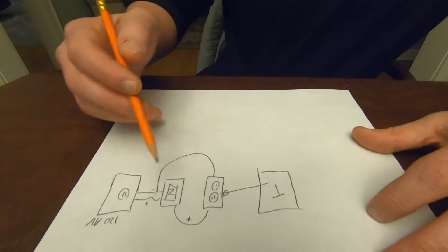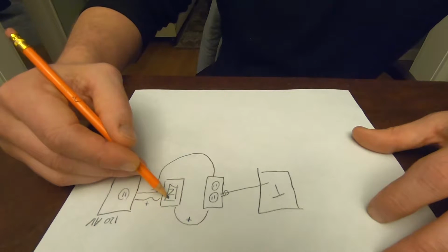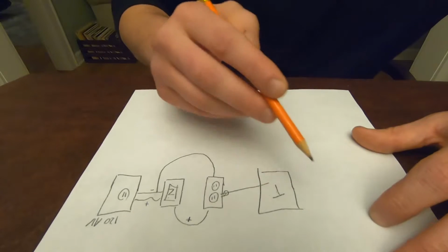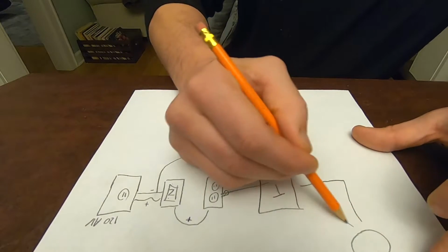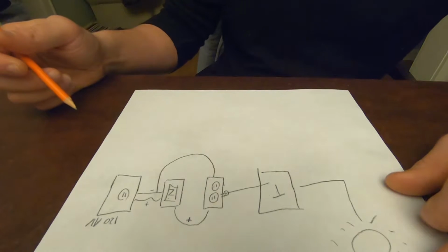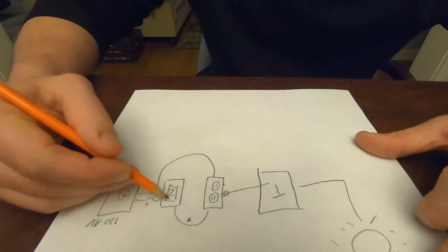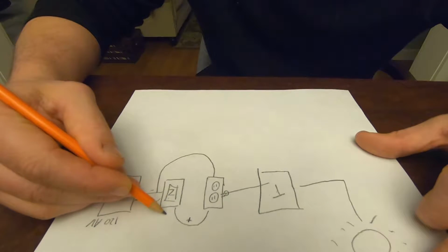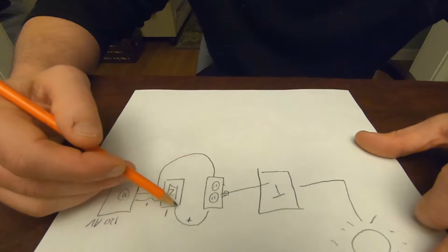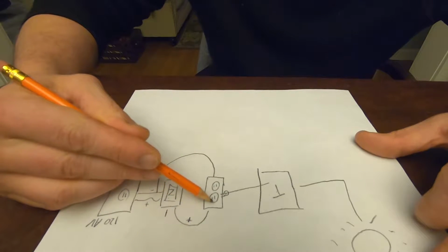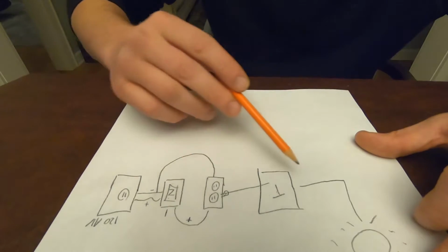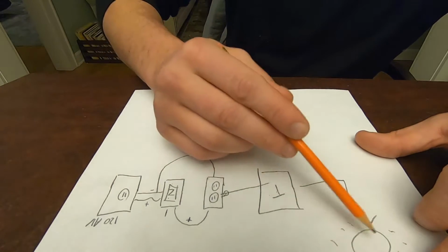So when you give this thing the command to turn on or off, it controls the power to this outlet, which controls the power to the transformer, which controls our lights under the cabinet, right? And when we tell this to turn to a percentage, to dim the lights, brighten the lights, it's going to vary this load line to this outlet that the transformer is plugged into, therefore dimming the light.